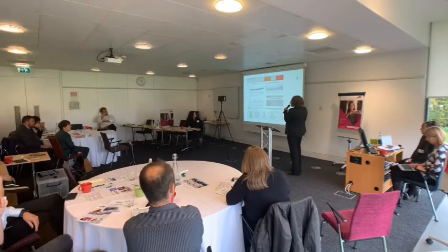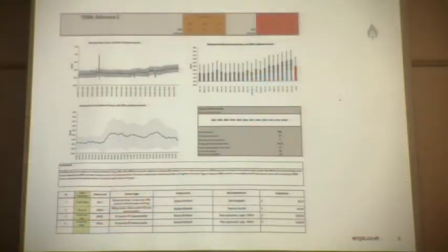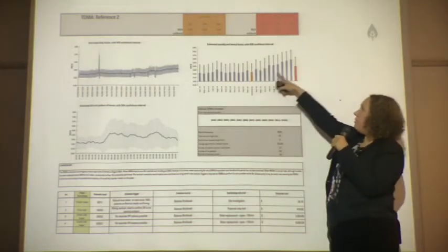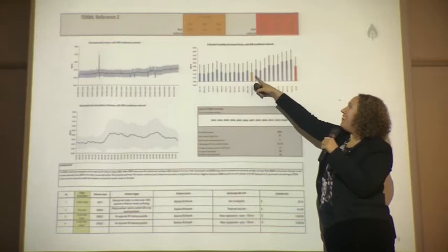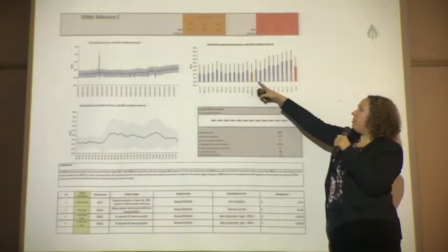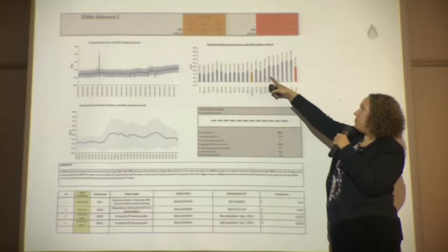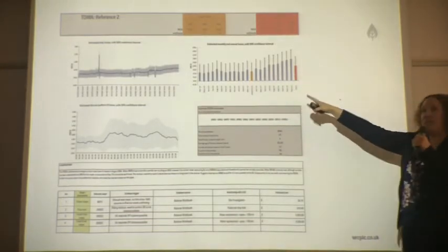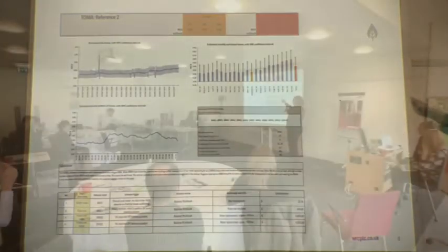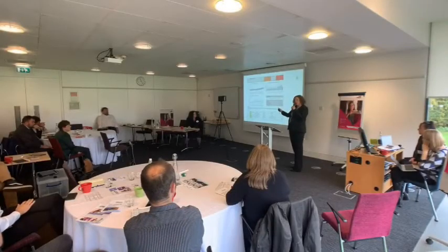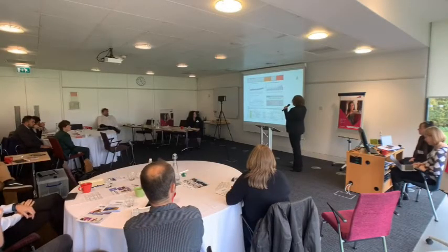Second example here then of another DMA, as I call them, or tiles you might hear them called, or TMAs, or upstream area, lots of different words are used. So this is just an example of a much wider uncertainty band, but you can actually see there's a rising pattern. So even if the real losses were sitting at the bottom of the uncertainty line, it's rising, and so it's a growing problem. So you might want to prioritise this area to try and find out, is that a metering issue, or is it a growing leak in the area?